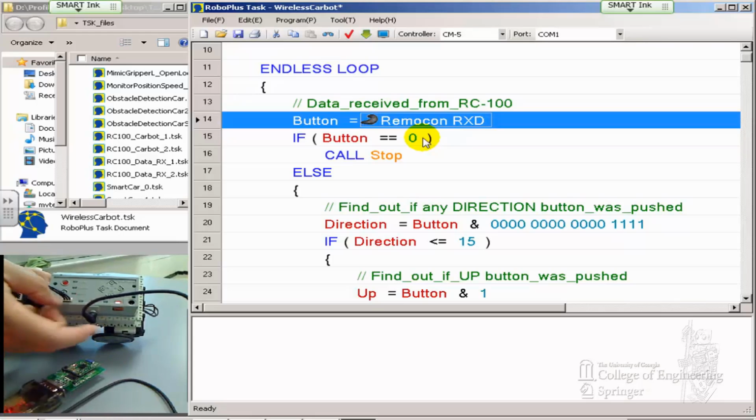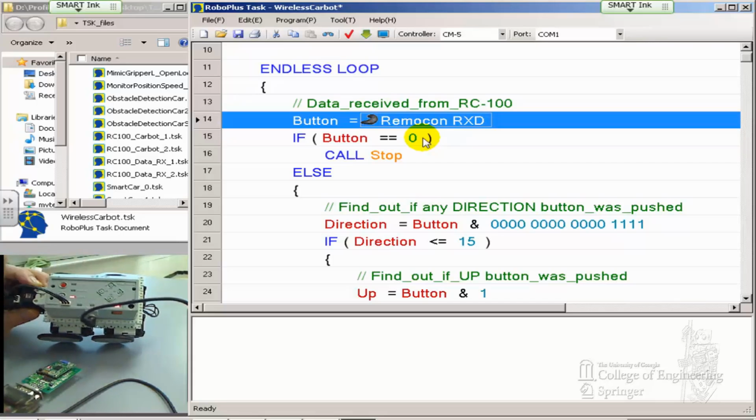If you unplug it and then check, I'm supposed to receive through my own little ZigBee chip. Why? Because the controller didn't have enough COM ports. They had only two COM ports, one to talk to its old servo and sensor, and one to talk to the outside world.